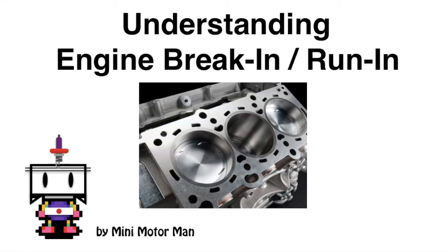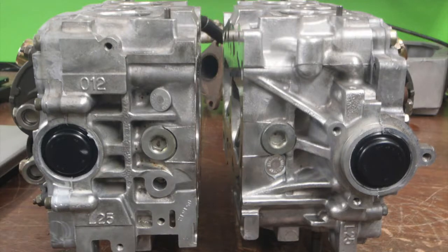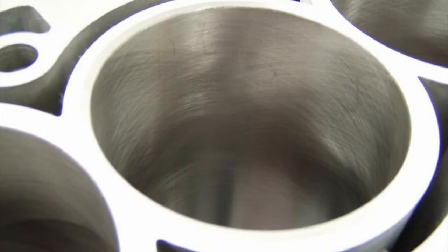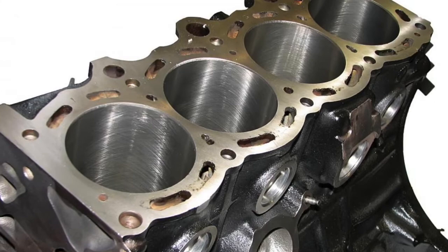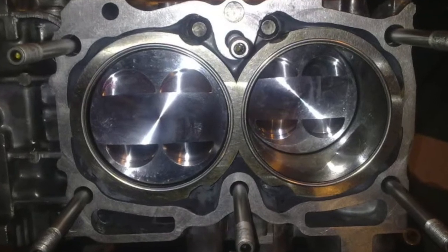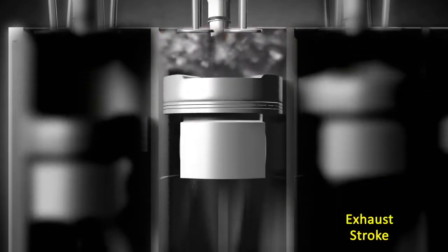Now I apologize if this sounds a bit winded, but here is now where all is going to start coming together. Now that we know that two pieces of metal, albeit very flat pieces of metal, can be used to seal two surfaces together, we now can start to see how this applies to the combustion chamber, namely with the piston rings and the cylinder, which both happen to be made out of metal. If we have the moving surface, in this case the piston, and the stationary surface, in this case the cylinder wall, very close to each other and finished to that microscopically flat surface we were just talking about, then we can create a good seal against the expanding gases and transfer more of the power to the crankshaft instead of having it just leak by. Sounds good, right? Unfortunately, there's a problem.